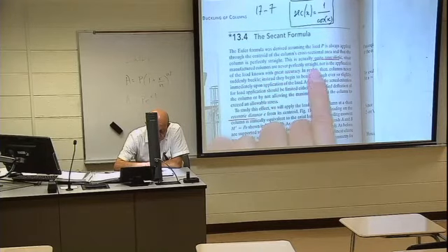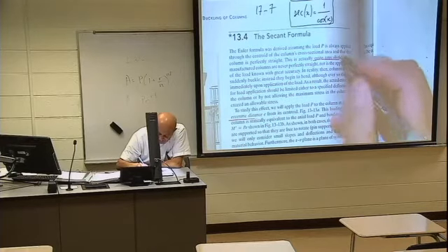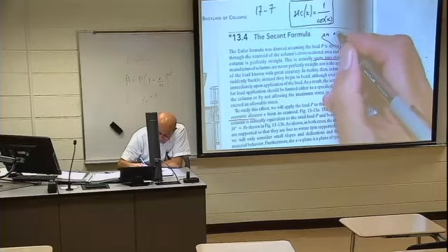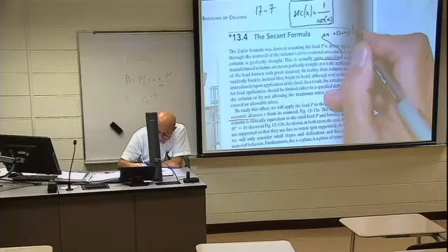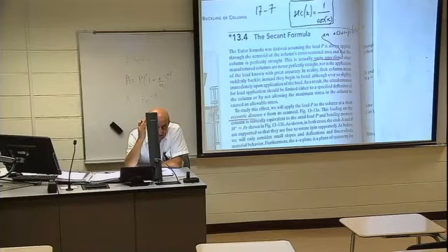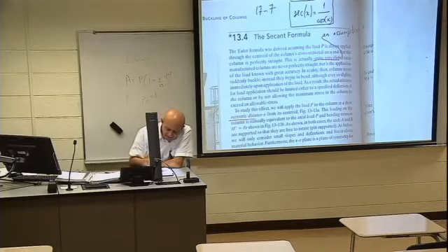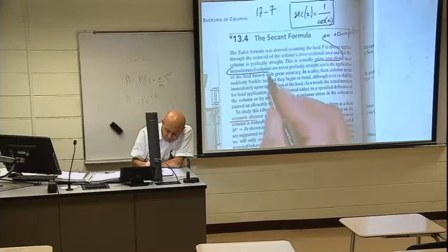This is actually quite unrealistic. What is unrealistic? An assumption. That means that we dealt with something that is not realistic, since manufactured columns are never perfectly straight. So please, that is very, very important to know.